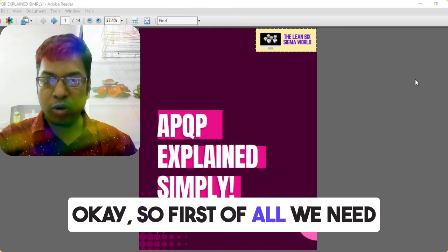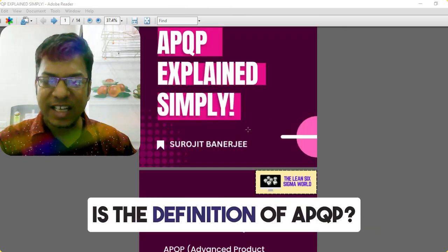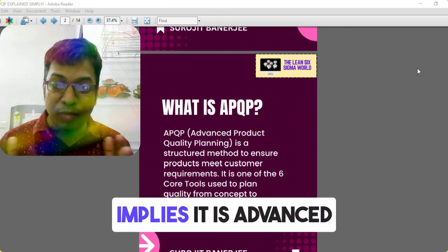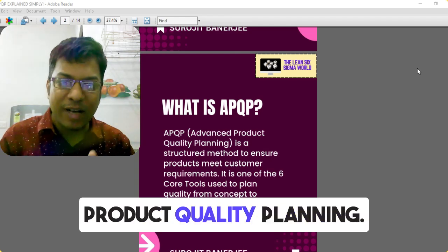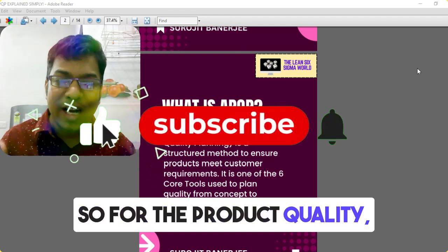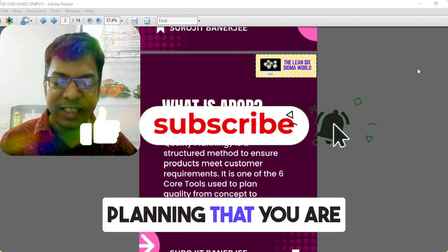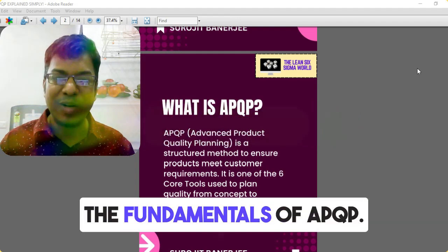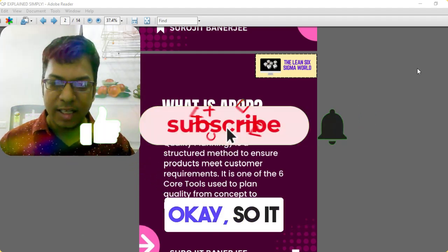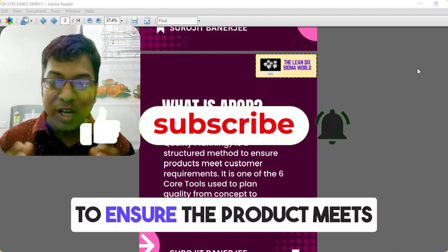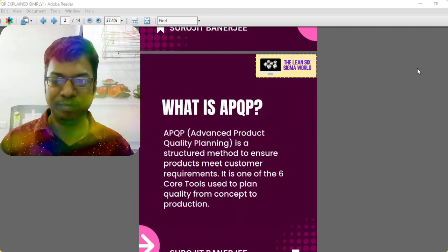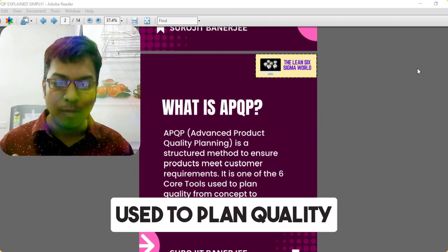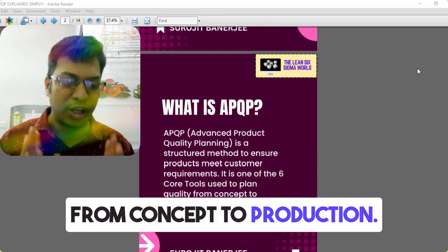Okay, so first of all, we need to understand what is the definition of APQP? What is APQP? So APQP, as the name implies, is advanced product quality planning. So for the product quality, what are the advanced planning steps that you are going to take so that you can meet the requirements of the customers? That is basically the fundamentals of APQP. Okay, so it is a structured method to ensure the product meets the customer requirements, and it is one of the 6 quality core tools that is used to plan quality from concept to production.